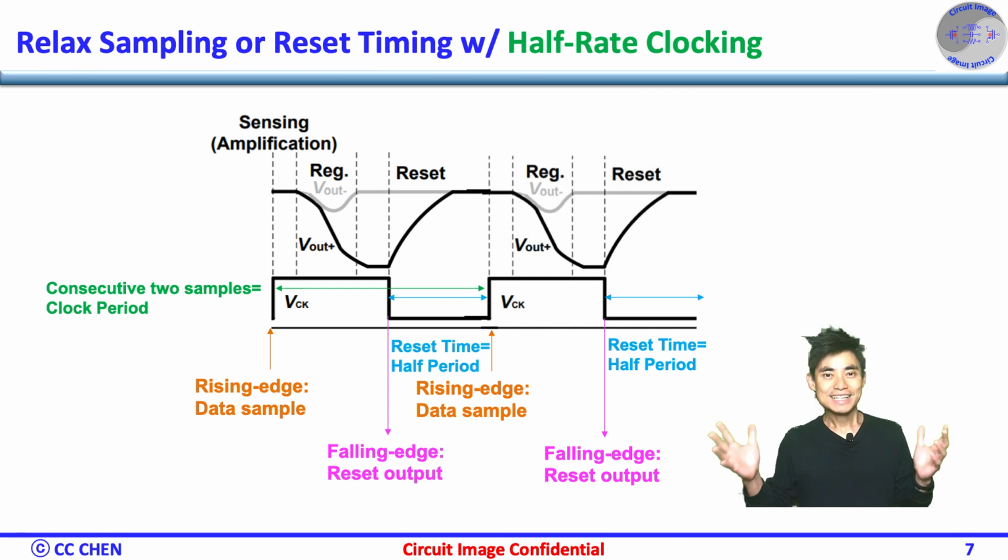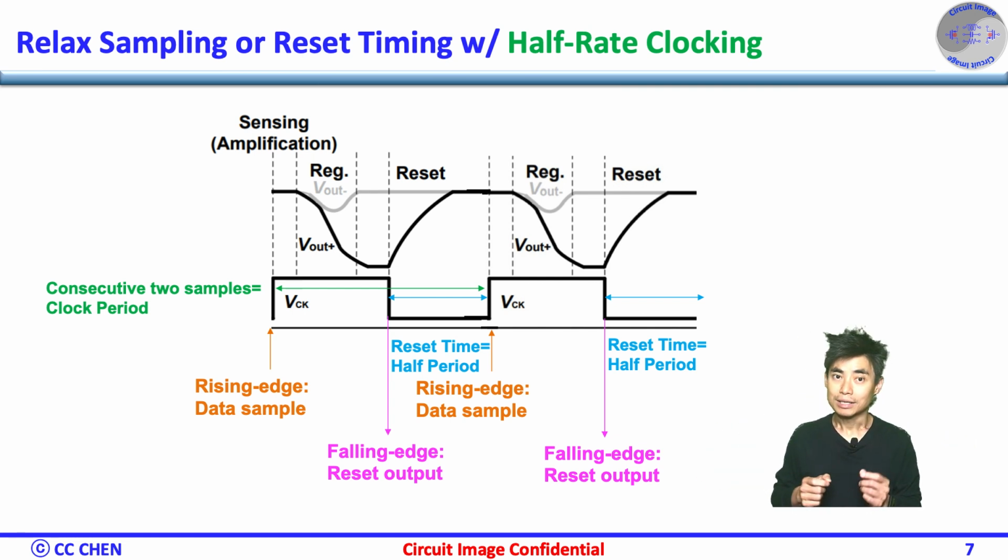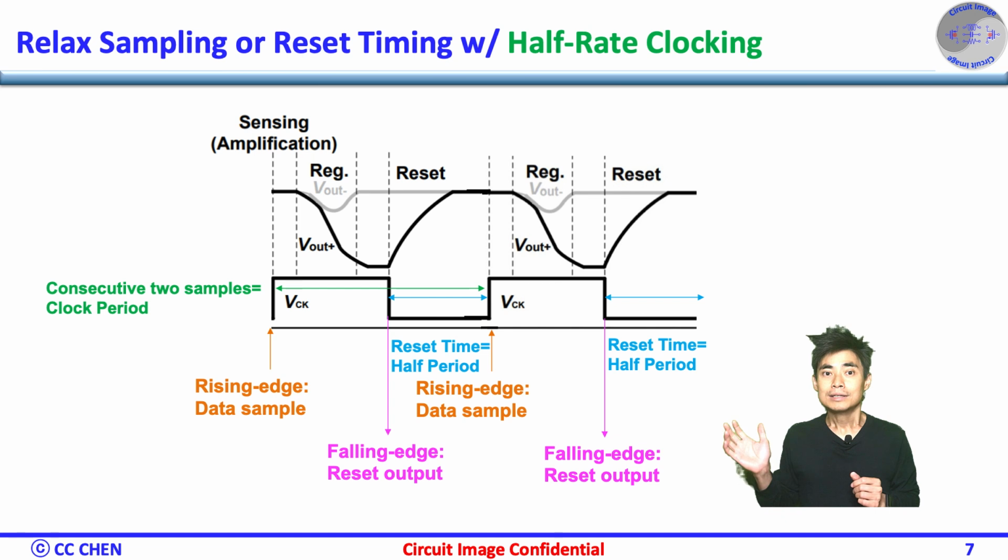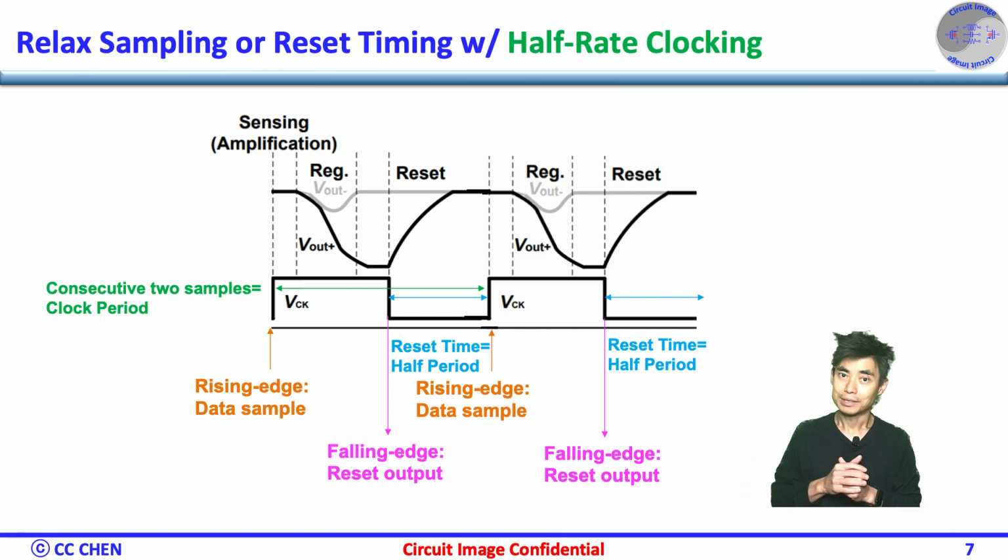Correct? Similarly, if we use the clock's falling edge to reset the sampler's hysteresis, then the sampler would have twice the time to reset the previous state. Therefore, the samplers used either in the CDR or DFE may have more time or operate at a higher data rate if the half rate clocking is used as the sampling rate.